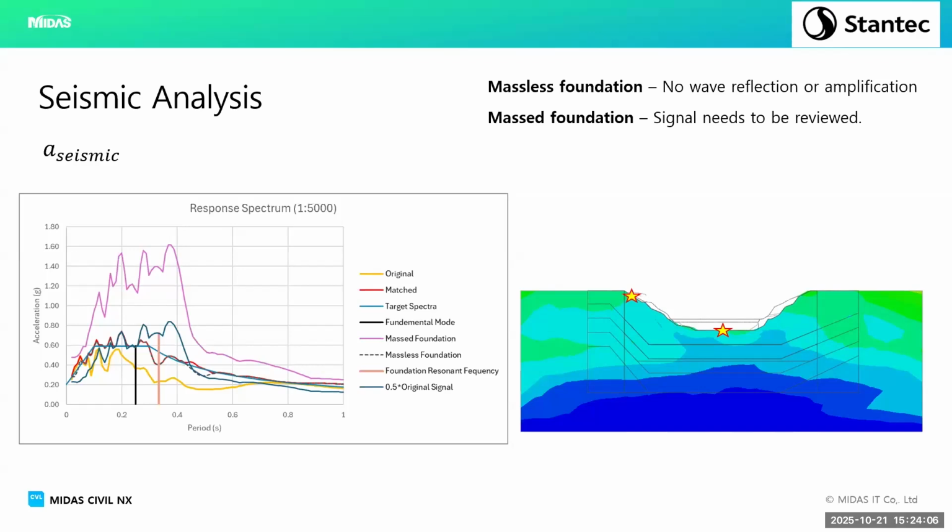This is particular to New Zealand, with softer soils and larger events: you can't take a spectra from a code. I think the Geotechnical Society might like that I'm saying this, but essentially you have to look at shear strains and plastic response of the foundation. So what one should do for complex geology, and that's why it's important knowing what geology is there and how it behaves apart from liquefaction,